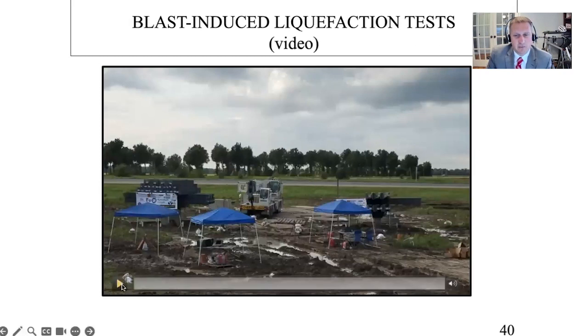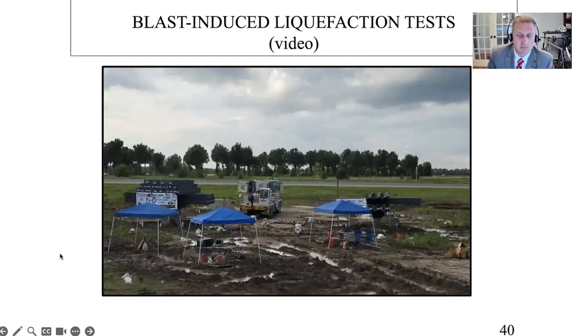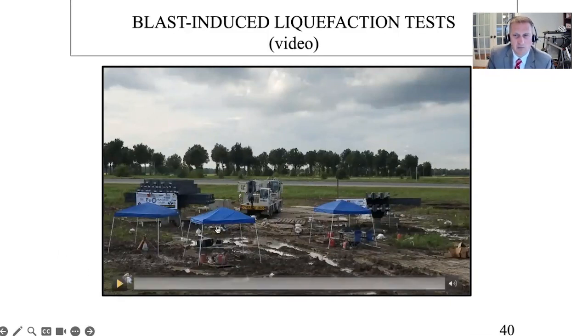This is a video that shows the blasting, and this one was done for the center shaft and the pipe pile. We have some surveying instruments set up outside of the blasting ring. This is the data acquisition for the strain gauges that are set up as well. And then there's a couple of cameras at different locations. If you have time at a different time, there are some videos showing how we did this blasting if you're interested in more information.